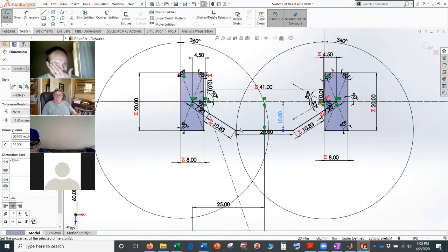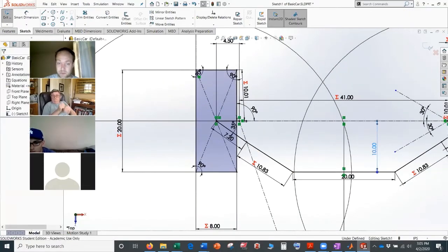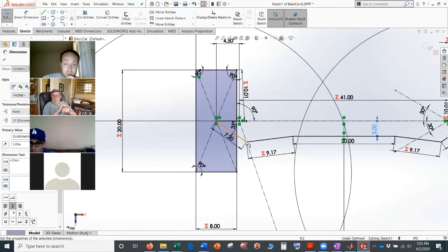It's also bad because, so this is the moment arm, so this is what it's spinning about. So your tire's spinning about this point, and you're pushing here. So ideally, you would push along this axis, basically, right? You want to be pushing normal to the moment. Anytime you're trying to make a moment, you want to push normal to it, right? So here we want to push normal to it. So we want to move this back closer to like maybe 3 inches for this setup, right? And that way we're pushing a little bit more normal to the line between here and here.